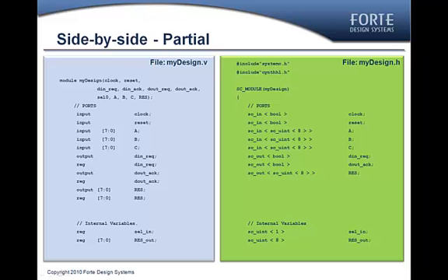Here we see a side-by-side of some of the lines for each code sample we've just seen. I've removed some lines to make comparison easier. Again, the module definitions are very similar, except that in Verilog you include all port names in the module definition itself. Port definitions then follow, again very similar for the two languages. Internal variable definitions follow that.